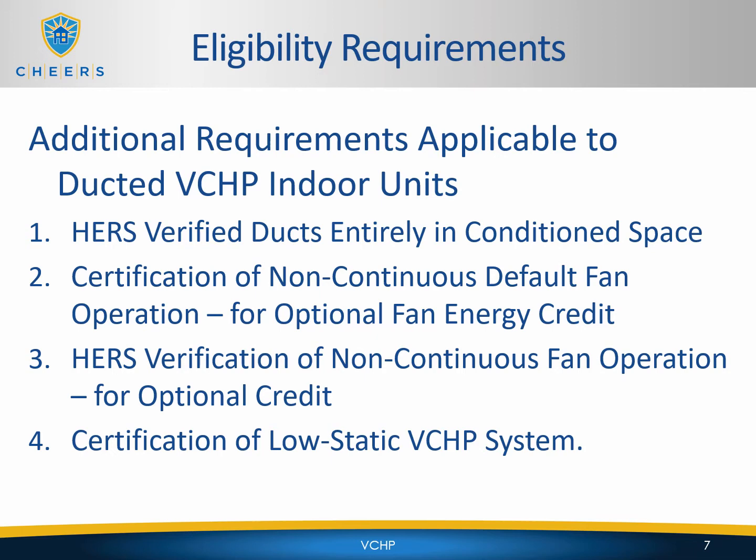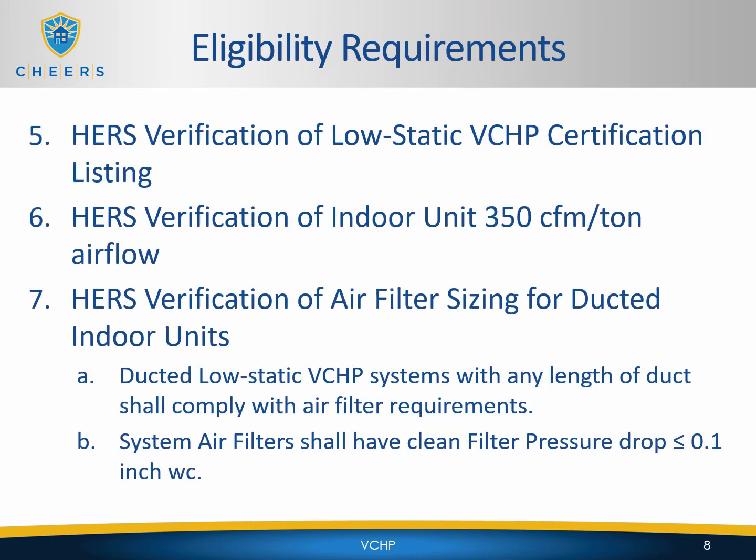Next, we have certification of low static VCHP systems, HERS verification of low static VCHP certification listing, HERS verification of indoor unit 350 CFM per ton airflow, and HERS verification of air filter sizing for ducted indoor units. Now this is ducted low static VCHP systems with any length of duct shall comply with the air filter requirements, and system air filters shall have a clean filter pressure drop less than or equal to 0.1 inches of water column.